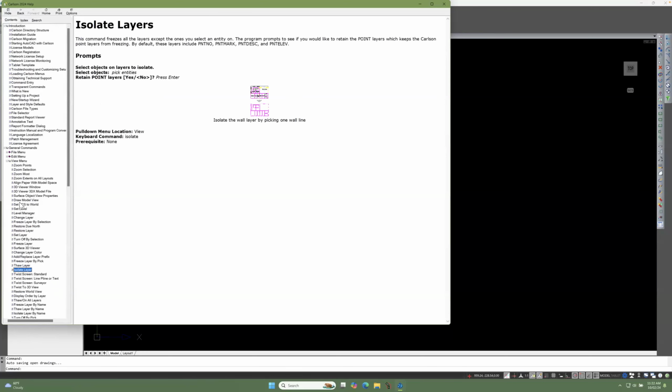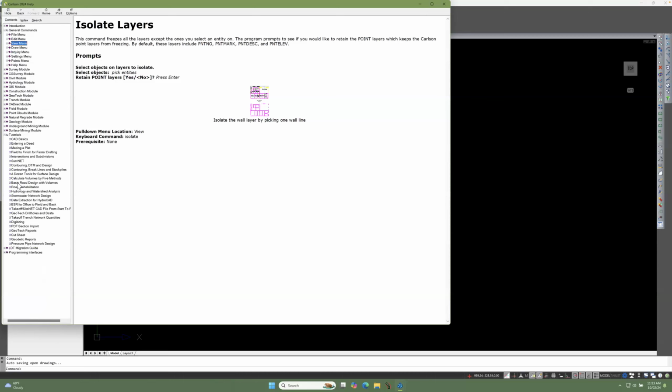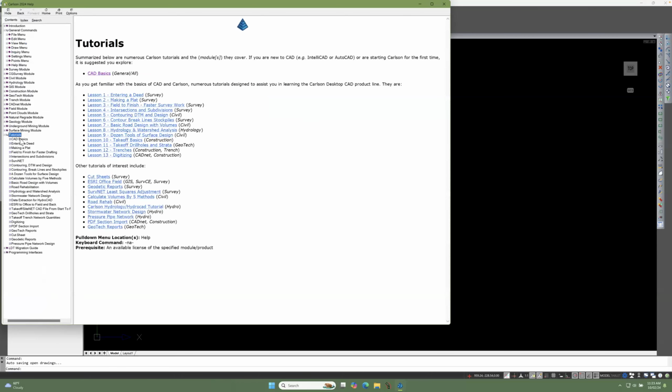All right, so the help system is going to give you a lot of information, and I would really focus your viewing down here under tutorials. And there's all kinds of different tutorials for different types of processes in Carlson, like how to enter a deed, how to make a plat, how to do contouring, how to do basic road design with volumes.